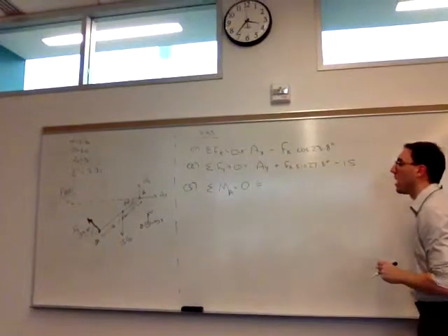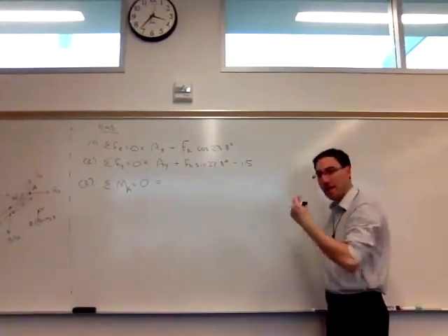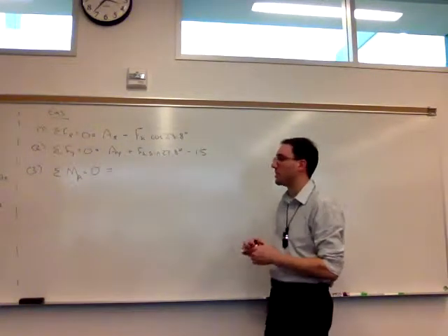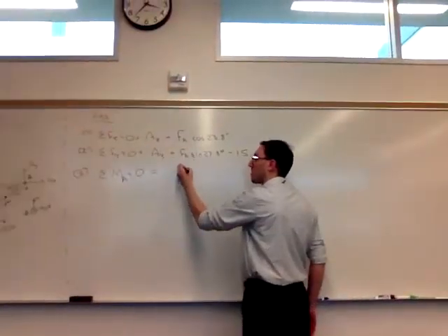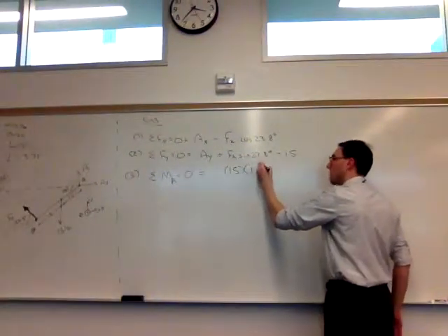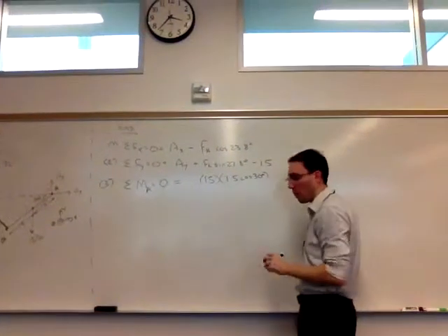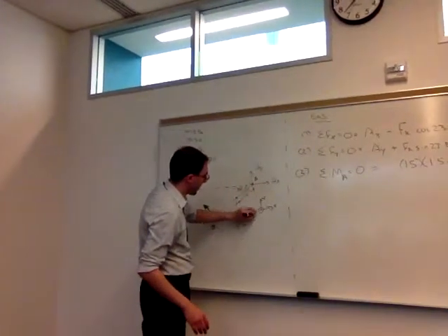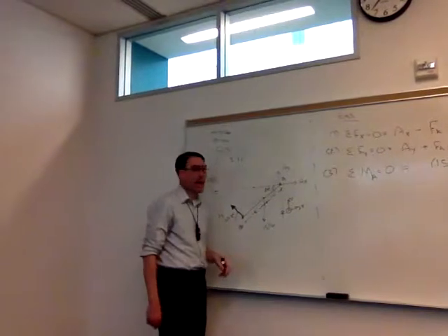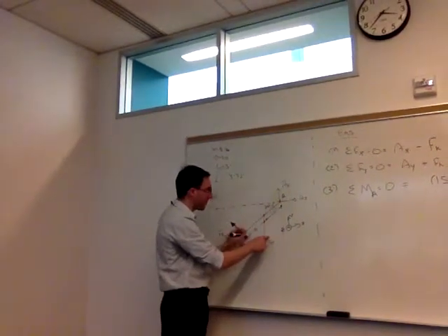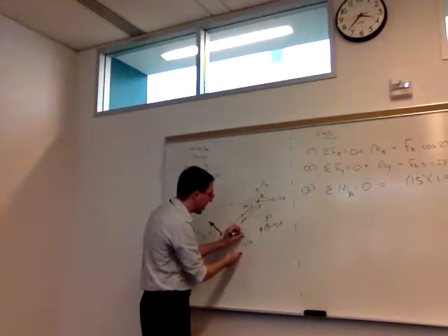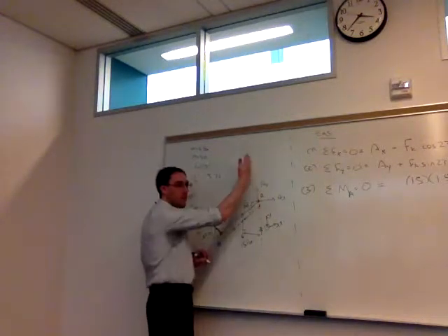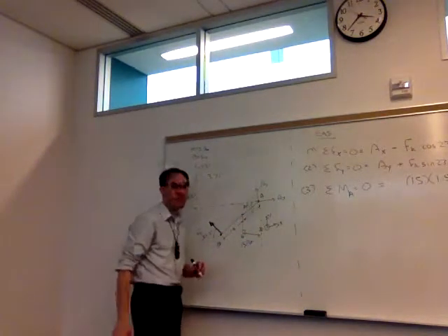This equation will be a little bit more complicated than the first two because, again, this involves forces and distances, perpendicular distances. So what is my right-hand side going to be for equation 3? Right, so that's the one piece of it. So remember, back when we were first doing moments, we were always using the perpendicular distance between our force and our point. So if we want the moment around A, for the 15-pound force, this is already completely vertical. The distance we need to use, that is this perpendicular distance between this line of action and the parallel to that line of action that passes through A.